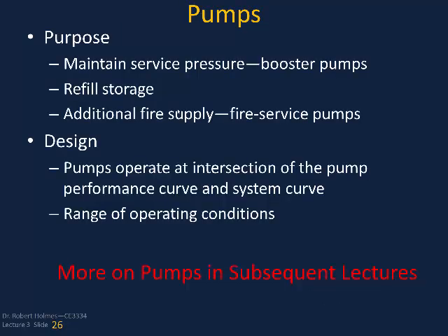All right, so if we look at pumps, we're going to talk a lot about pumps in the next several lectures. Essentially the purpose is threefold for the most part in our water distribution systems. It's to maintain your service pressure, like booster pumps, it's to refill your storage areas, and you might have fire service pumps designed into your system at different places to enhance the fire supply to those areas that would have high need.